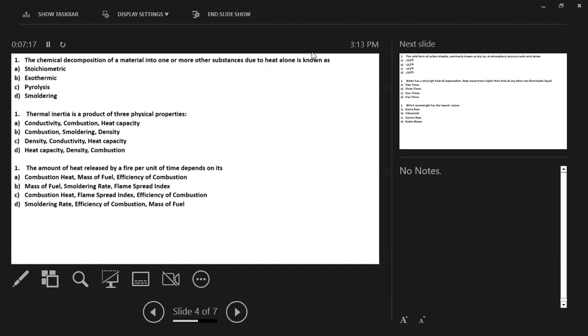So heat transfer per unit of an area. So I can say density is the one that is, of course, there. Second thing is the capability of the material to conduct the heat. We gave the example of steel and glass. Steel has the capability to sustain, right? While the glass does not have. It means conductivity is the second important parameter. And the third, if you remember, was the mass. A single sheet of paper will be consumed very quickly. If I have a bundle of paper, it will take much more time to consume. So that's the thermal inertia: density, conductivity, and heat capacity.